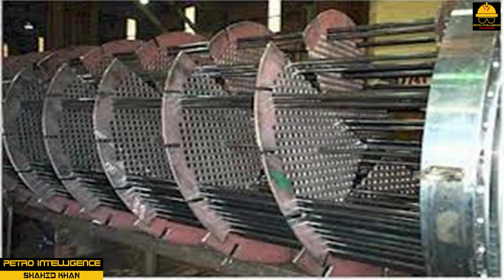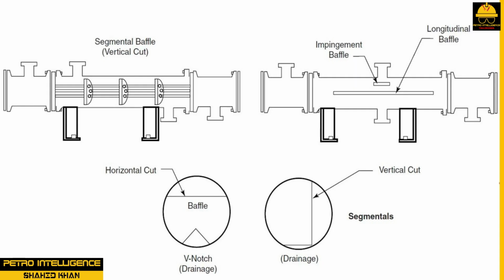Baffles. Internal baffles are structurally important to the performance of a shell and tube heat exchanger. Baffles provide the framework to support and secure the tubes and prevent vibration. The baffle layout increases or decreases fluid and directs flow at specific points. Tube-side baffles, or pass partitions, are built into the heads to direct tube-side flow. Tube-side baffles may be cast or welded in place.